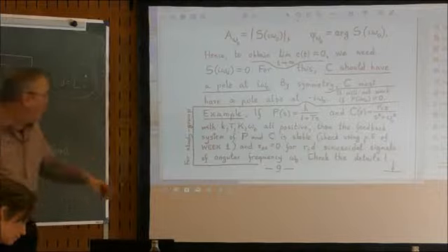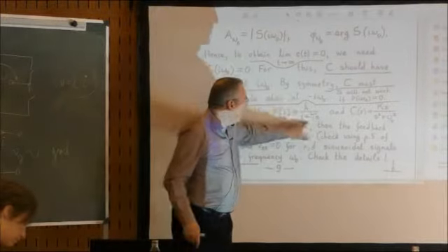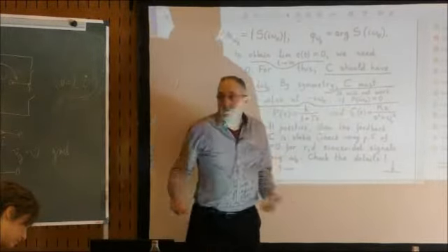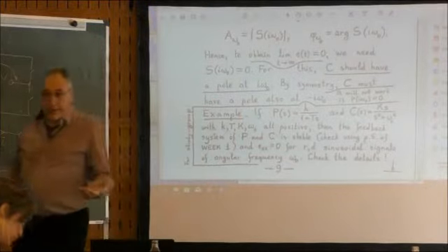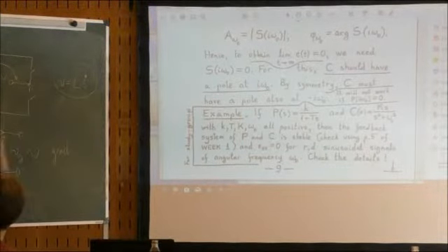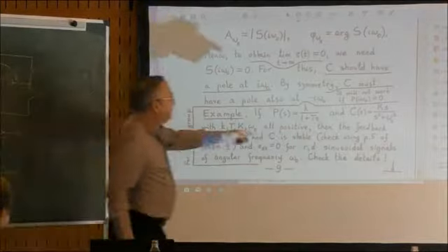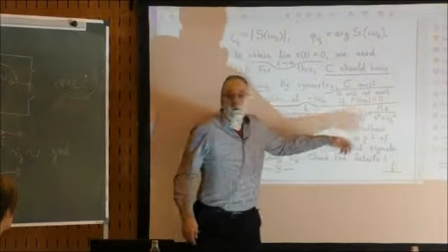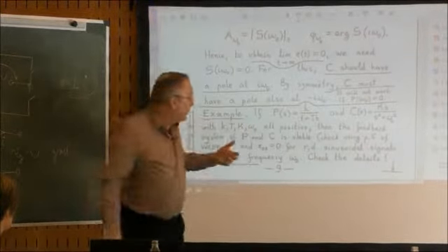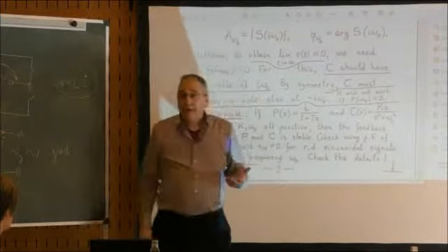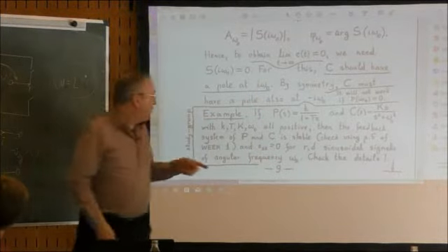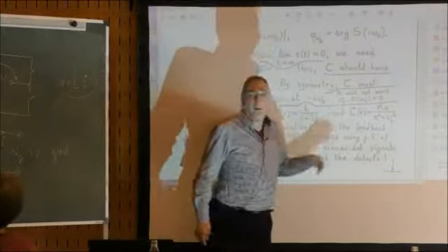So it's exactly this situation, and I need to eliminate grid frequency both in the disturbance and in the reference, and so I can use this controller, and you can check that this controller indeed does the job, which means we have to check that the closed loop system formed by this and this is stable.